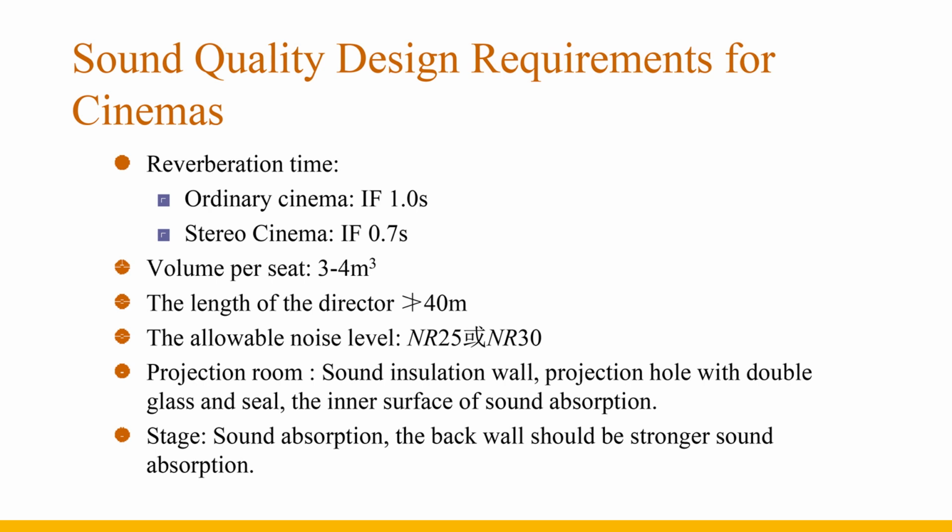Cinemas include ordinary cinemas and stereo cinemas. The loudspeakers of ordinary theaters are arranged behind the screen, and the playback system is used, which requires that the theater hall can reproduce the sound effect, and the acoustic characteristics of the hall should not affect the playback effect. Since it is a playback system, there is no acoustic feedback problem, and the volume of the speaker can ensure sufficient loudness in the auditorium. Therefore, the reverberation time should be short.